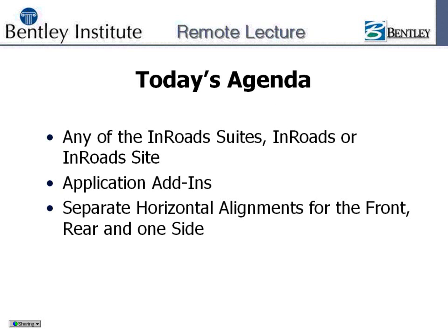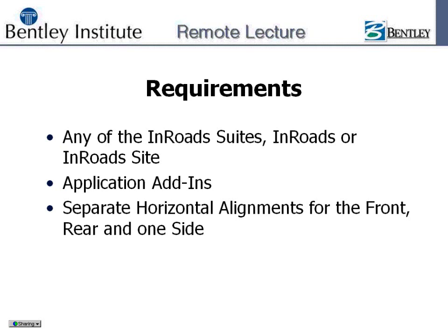Okay, the requirements. You have to have any of the InRoads suites, InRoads or InRoads Site, loaded up. I believe the lot layout commands were introduced in 8.2, so most people on the line should have these tools. They are an application add-in, so to get them to come up, you have to go to Tools, Application Add-ins, and then they'll be added under the Geometry pull-down.